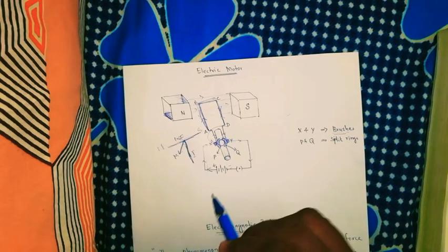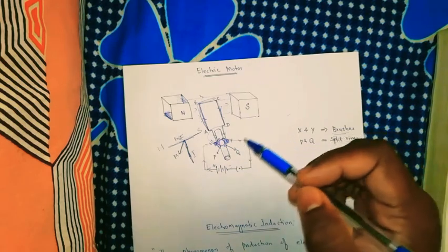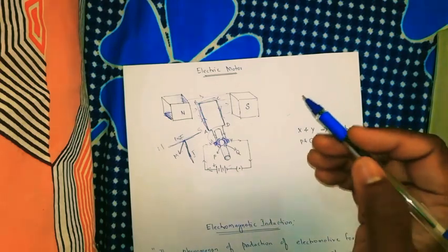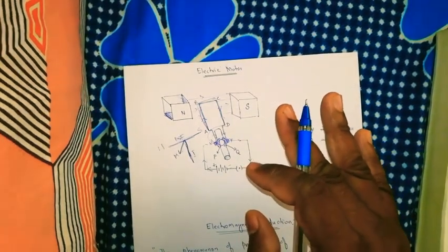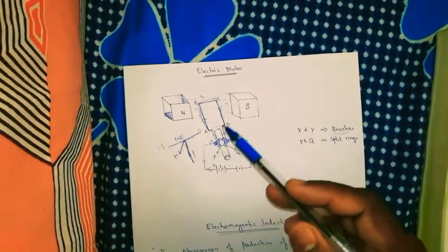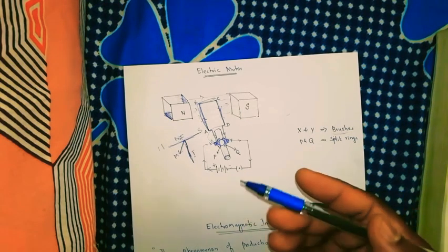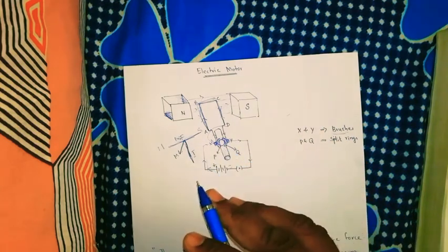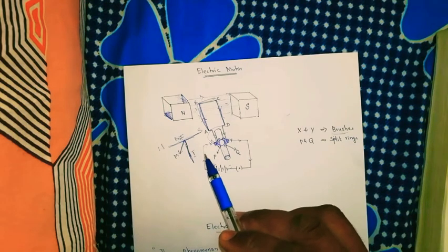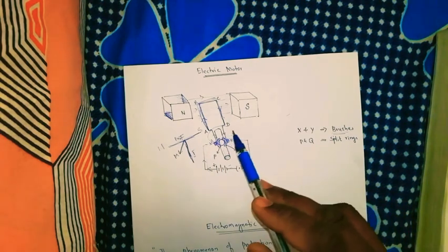Can you understand now? So the reversal of the current also reverses the direction of the force acting on the two arms of ABCD. Thus, the arm AB of the coil that was earlier pushed up is now pushed down. Clear? So this is how the full mechanical work takes place in electric motors. So what happened? First it moves in a clockwise direction. Therefore the coil and axle rotate another half turn in the same clockwise direction. So this is how it works in electric motors.